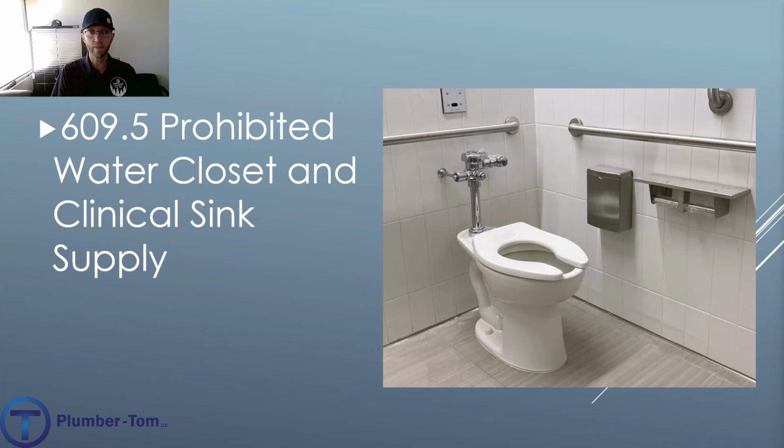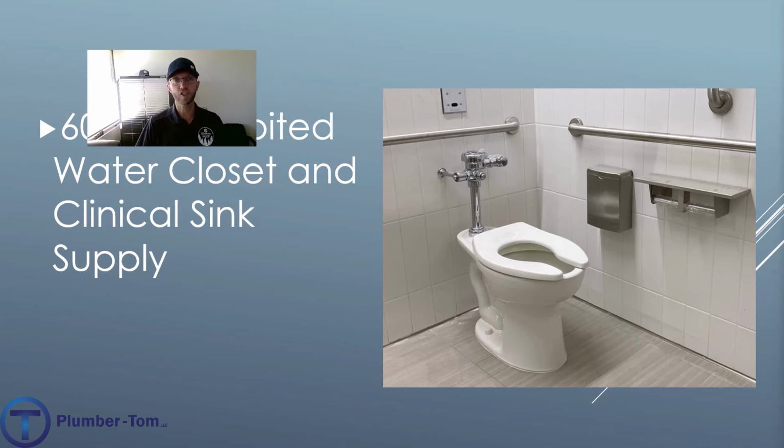What this is talking about is that for both water closets and clinical sinks, you'll have basically that toilet or that bowl, and it's going to have a flush connection, so the flushometer valve, that's great. But any other supply, like that hose faucet, should not be connected at all to the fixture. This way the flush valve can still operate and flush the fixture clean, but anything else that would supply water is entirely not connected to the fixture.